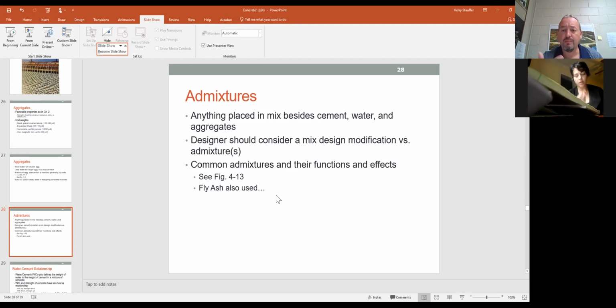But in order for them to pump concrete, it has to be of a certain consistency. So instead of thinking about something really thick, think about something more soupy, that they're able to actually run through the pump. But at the same time, it's not going to cause any segregation of your aggregate. So those are pretty neat. Really, besides pumping agent, I think the one that's much more common with pumping concrete that I've been around are called superplasticizers. So a superplasticizer will increase the flowability of the concrete.